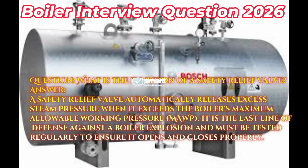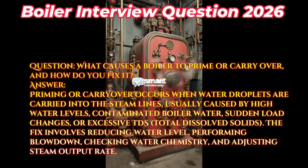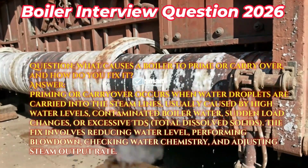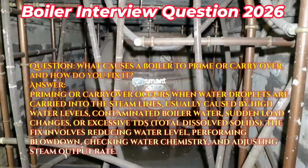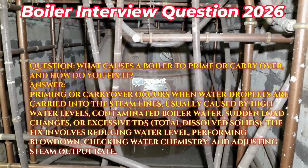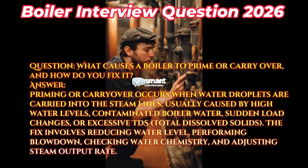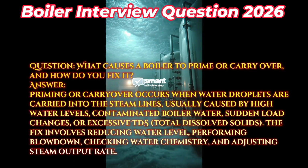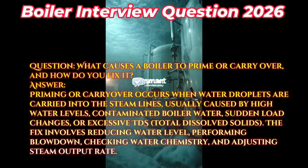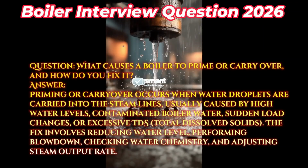and closes properly. Question: what causes a boiler to prime or carry over, and how do you fix it? Answer: priming or carryover occurs when water droplets are carried into the steam lines, usually caused by high water levels, contaminated boiler water, sudden load changes, or excessive TDS, total dissolved solids. The fix involves reducing water level, performing blowdown, checking water chemistry, and adjusting steam output rate.